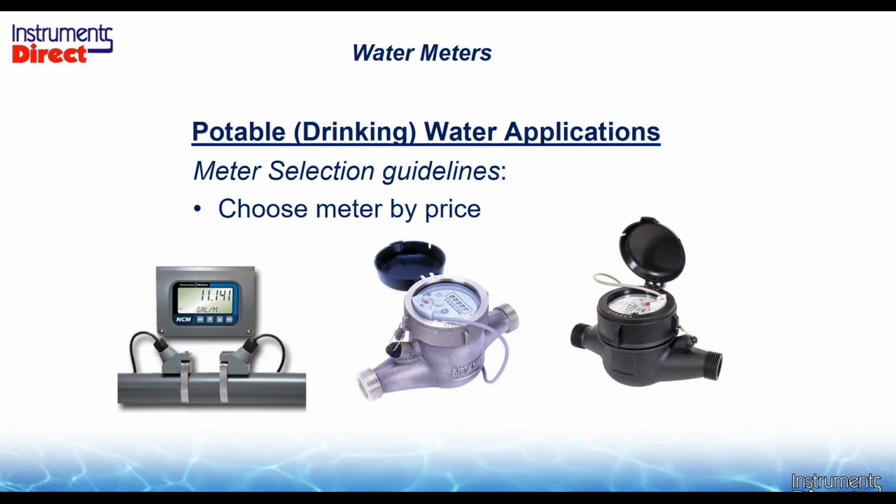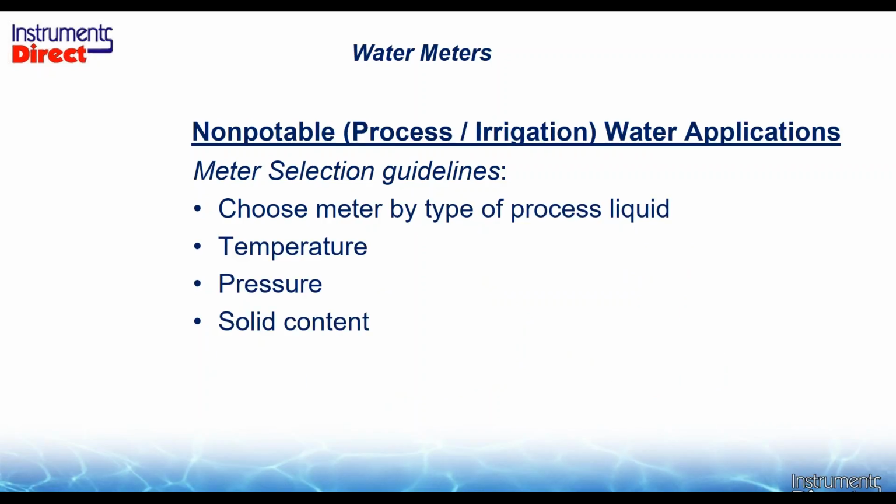So now I have a device that has a set of electronics that's sending a sound beam inside the pipe. There's a significant difference in cost there. So we went over here from a couple hundred dollars to $400 to $2,000. Well, why would I spend $2,000? Well, how much does it cost to cut the pipe and put it in? Sometimes you don't have that privilege. So it all depends on your price, on the type of metering selection that you're going to make.